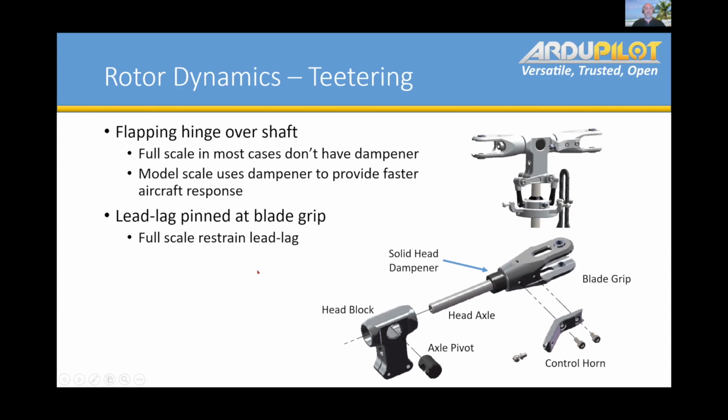the shaft. But then again, also for the lead-lag degree of freedom, in pretty much all RC helicopters, it's pinned, whereas with a teetering rotor system from full-scale helicopters, generally they'll restrain it and basically beef up the rotor system to withstand those loads.